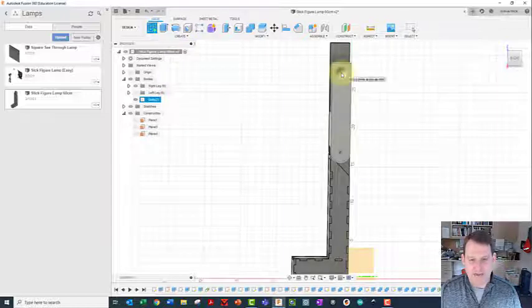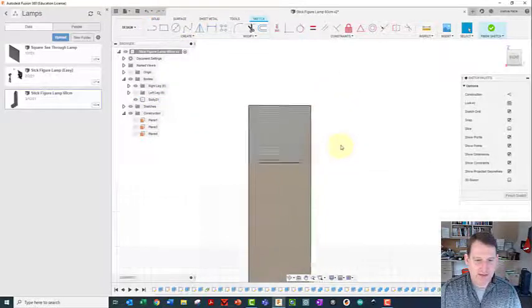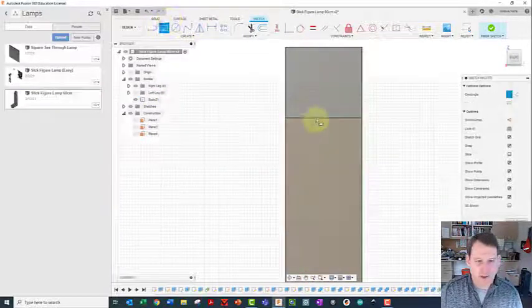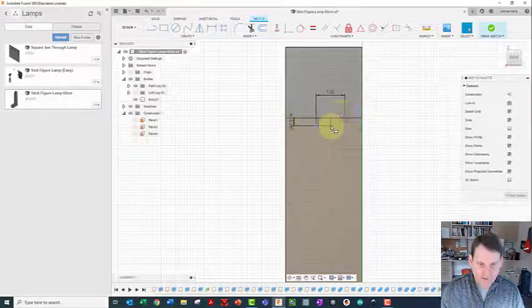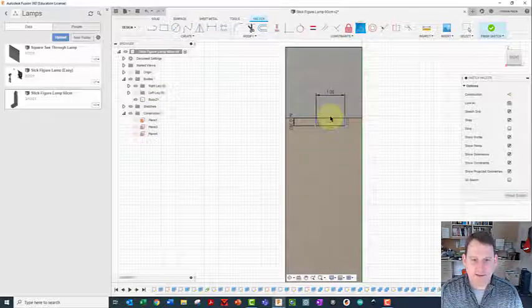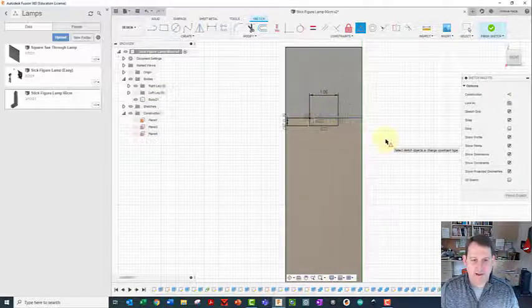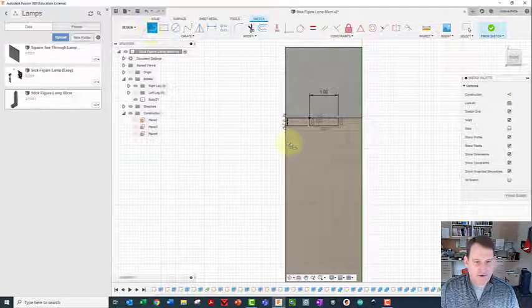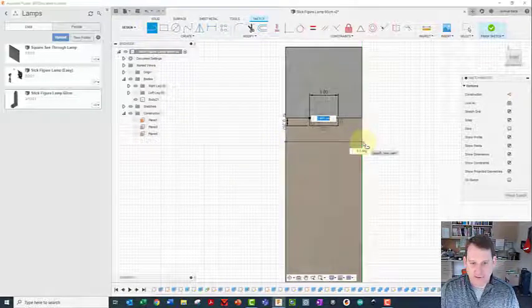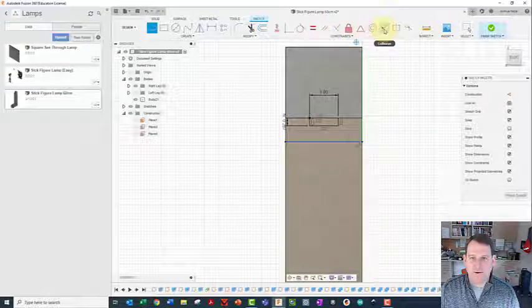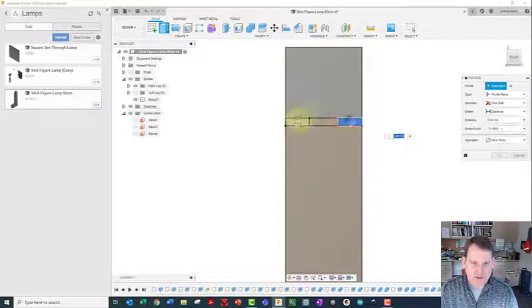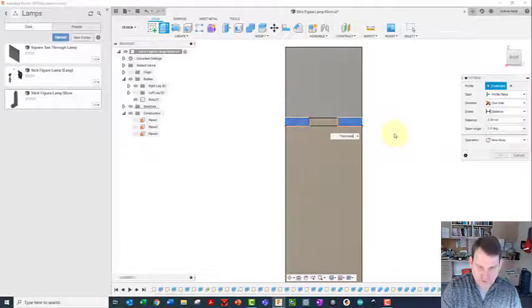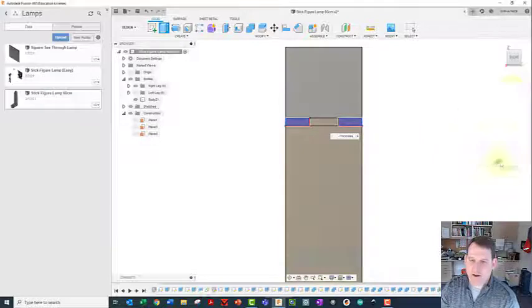I'm going to create, on the inside of the thigh, a sketch. And I'm just going to cut away. So this one's thickness. I'm just making that one tab that's going to go inside one. I'm going to center that on that. And then I'm going to just draw a random line right across there. Use my collinear tool and say, make that one line up with that one. And now I can extrude this and this. And I'm going to do a negative thickness across there and click OK.